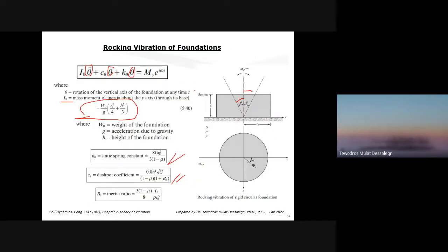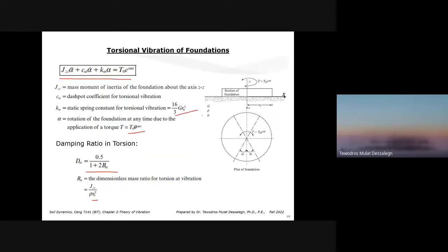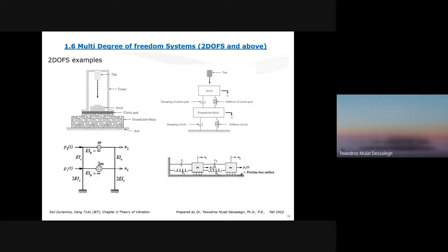So this is just for a 1 degree of freedom system. Usually if it's a foundation on soil, we treat it as a 1 degree of freedom system. And these equations, you don't need to memorize anything here. All this would be available to you when you do the design. Just be aware of what the equations are, what the terms are, and what they mean, the design philosophy, how to avoid resonance, what frequency you have to select, all that.